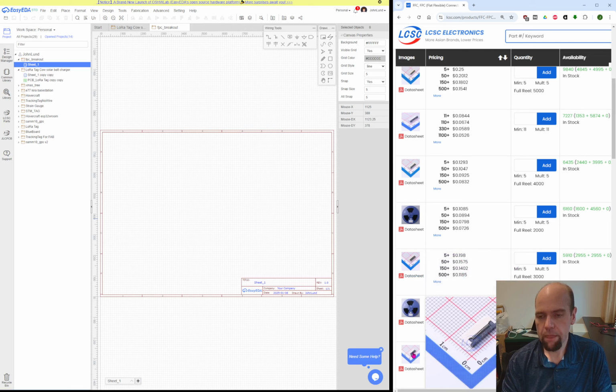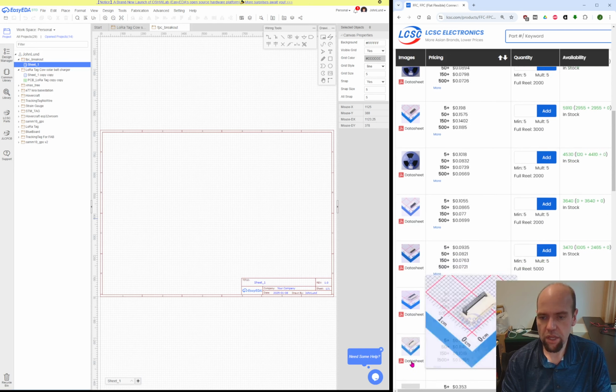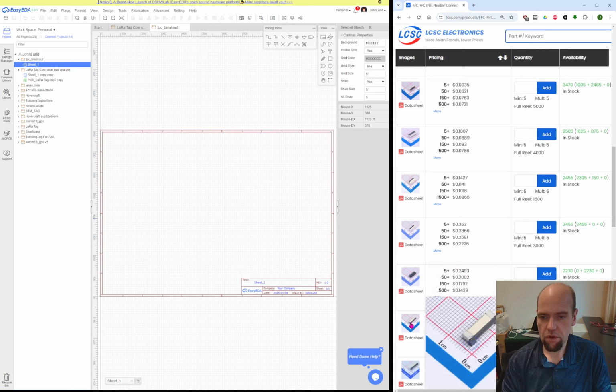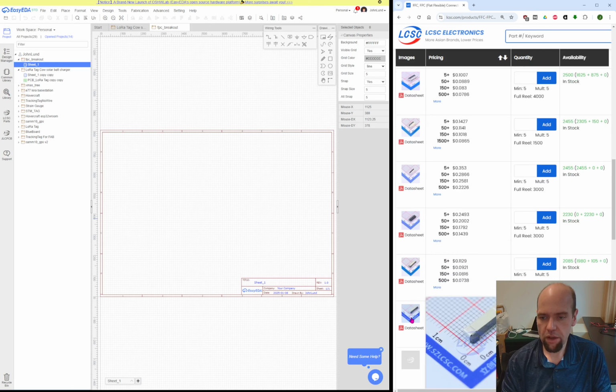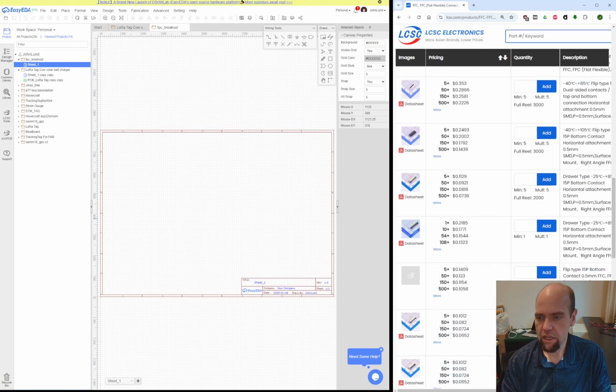So it allows you to have the FPC connector, the little ribbon, either pin side up or pin side down. The benefit is it gives you some flexibility in that you can connect your ribbon either way. The downside is you have to know which way it needs to go in, because if it's backwards, it'll just be connected backwards. So probably not something you'd want if the user was plugging in the cable. But if you're using the FPC connector just for you to be the one that assembles it, it's probably fine to go with a reversible connector.